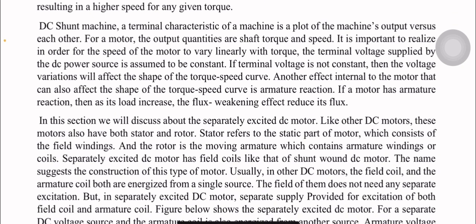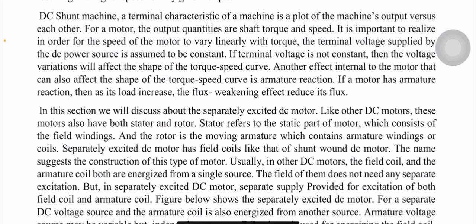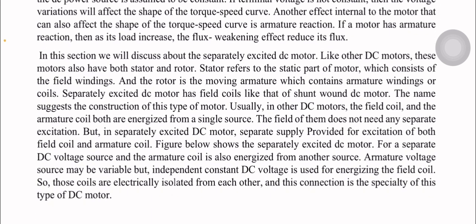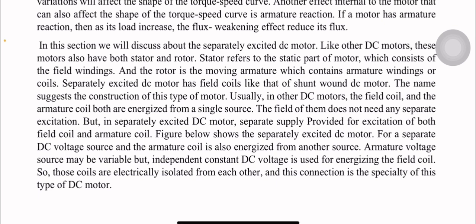Another effect internal to the motor that can also affect the shape of the torque speed curve is armature reaction. If a motor has armature reaction, then as the load increases, the flux weakening effect reduces its flux. In this section, we will discuss the separately excited DC motor.